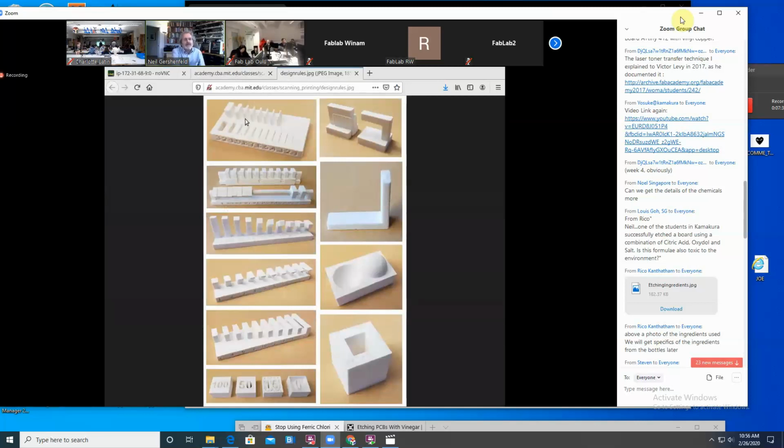And then in the opposite direction, I've made a gap. And there's a limitation for how close the gap can be before it fuses. The next one is a part around an axle, and in steps, I'm making the clearance smaller and smaller. And the question is how close it can be while you can still rotate it. And so all of those released, those parts didn't release.